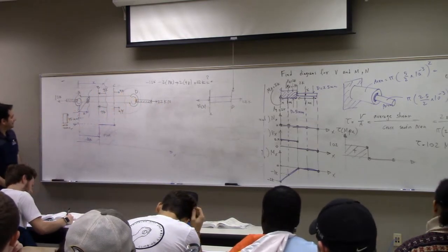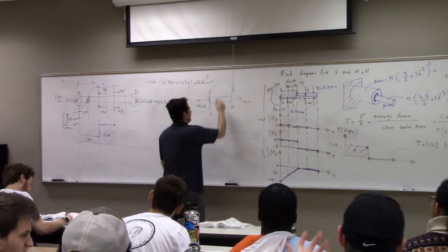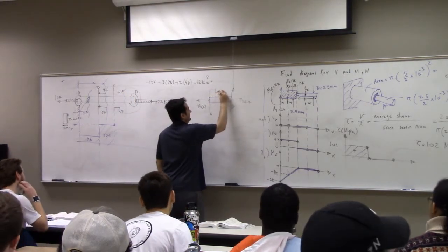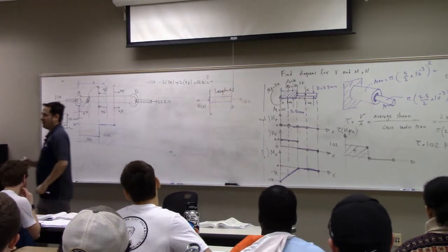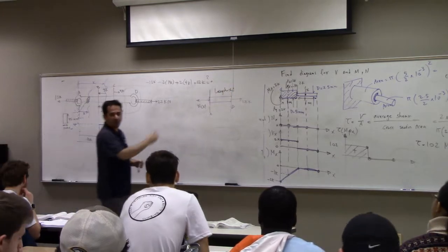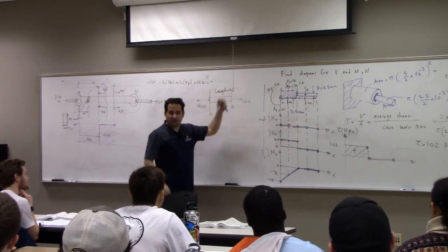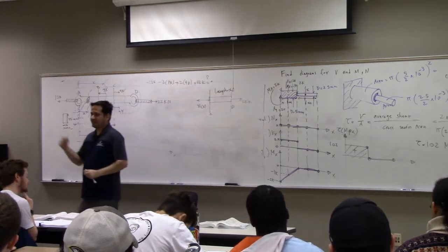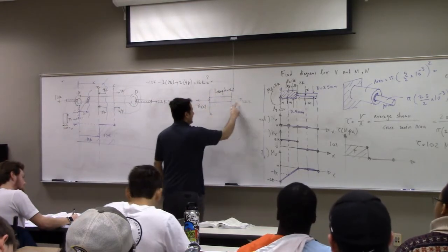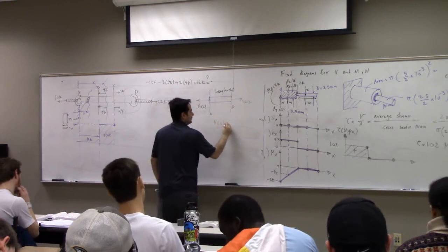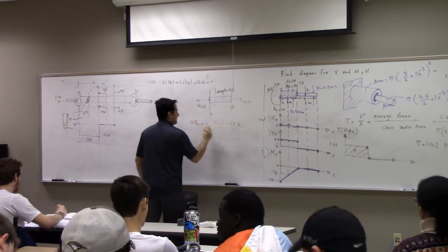What's the length? Length minus x. Why don't you need the length here? Because you're not drawing the moment diagram. If you draw a moment diagram, you multiply this shear by that, and in that case you really need to know the length. But here, the axial load is independent of whatever you have here. So N is equal to 22K, summation of force in x is 0.